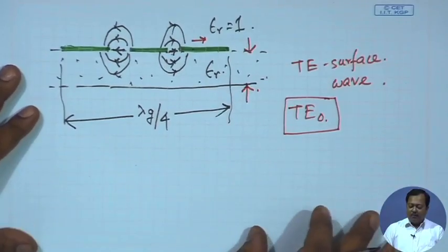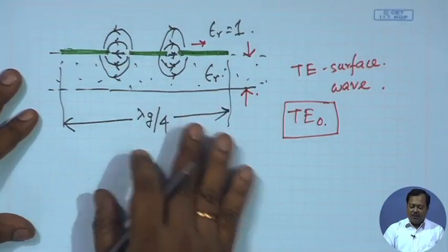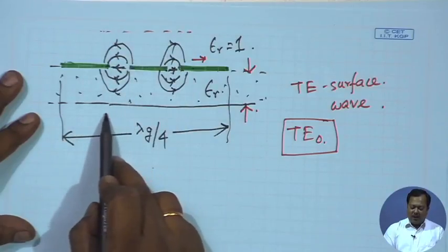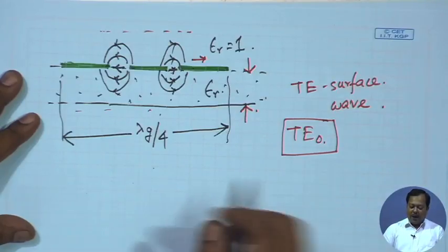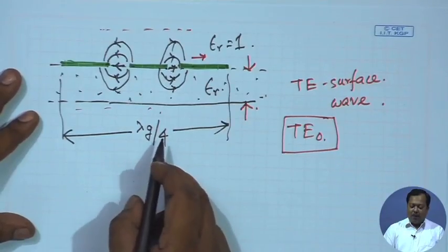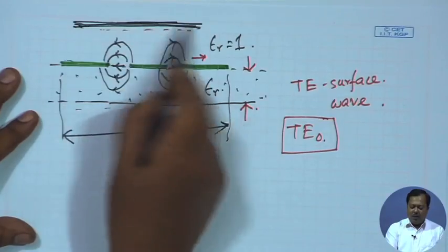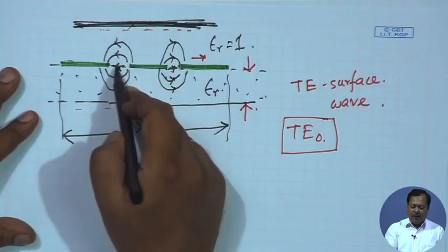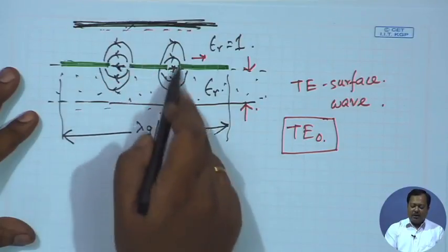So, most of the time for MMIC, the CPW line is not preferred, since you have to maintain the spacing for this fringing field as well as for the dielectric, because finally at the end of the day we have to go for some packaging, and packaging we do by using some metal box. And now if the metal wall, let us say it represents the metal wall of the packaging, is close to CPW line, then obviously there will be coupling between the CPW mode and this metal, and the mode characteristics will change.